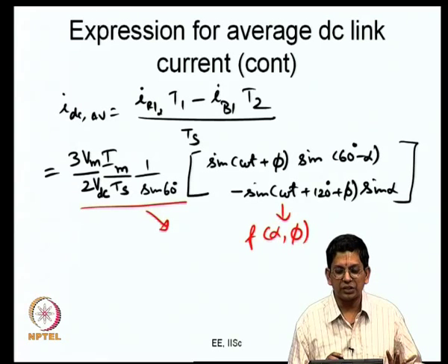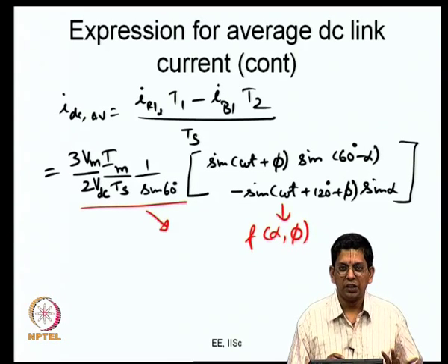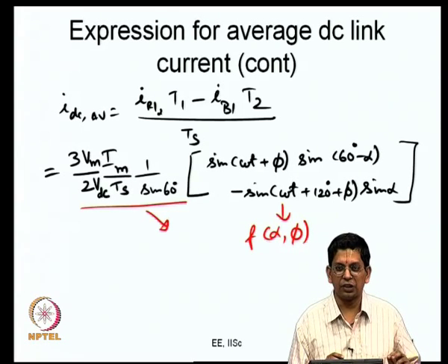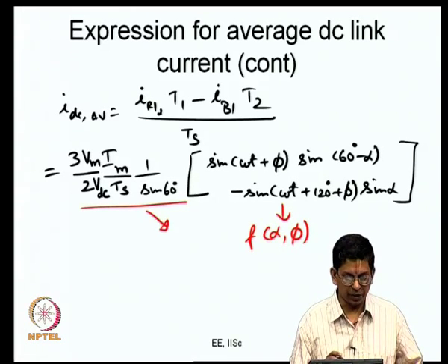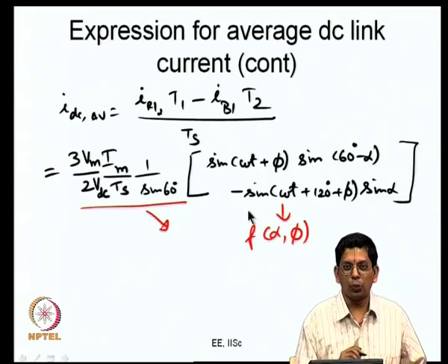And you should understand that this 2 level voltage source inverter is one of the simplest configurations of voltage source converters. Here you should be able to relate the DC side and AC side better. Then there are other applications, I mean there are multi level converters and so on, and in those cases you will be able to relate them in a much simpler fashion. So, this is a useful exercise in that regard, and you can just go about doing this now.